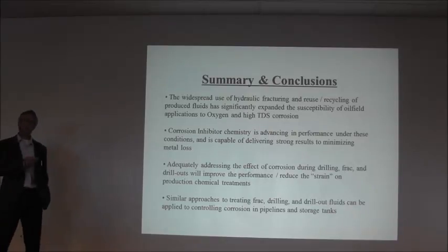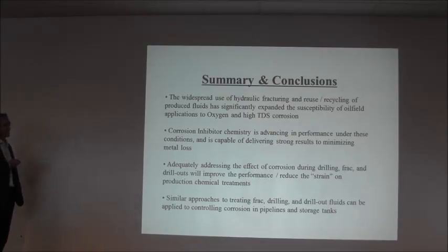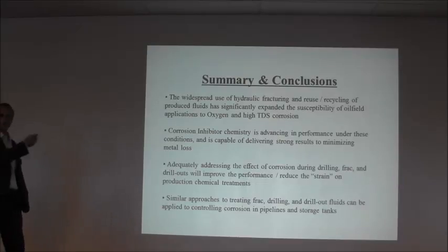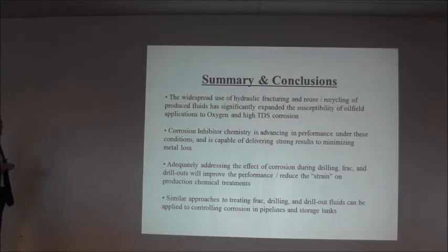And so by keeping that iron on the pipe wall wherever we possibly can, we are going to allow that friction reducer to do its job and not deprogram it. Originally, when the friction reducer grew up, it was an anionic flocculant. We just kind of changed the game a little bit and said, no, we don't want you to flock anything, we want you to reduce friction. But having something like iron in there will cause major issues on your stimulation side.